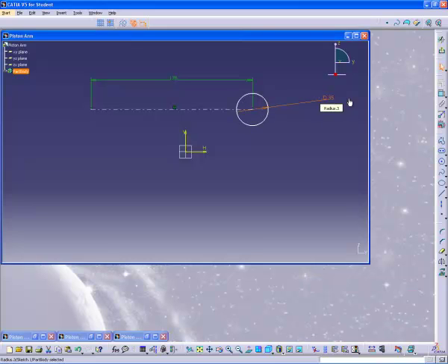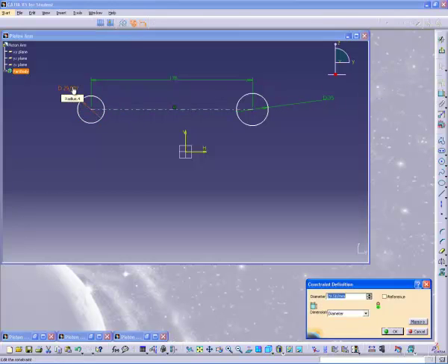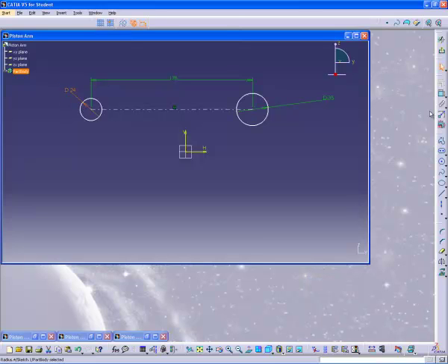Going to connect those two circles with a horizontal line, dimension that to 9 millimeters from our center axis. We're going to then mirror that horizontal line across our center axis and erase the unnecessary parts of those circles. Then I'm going to exit the Sketcher window and pad that first sketch. I'm going to mirror extent, pad it to 9 millimeters.